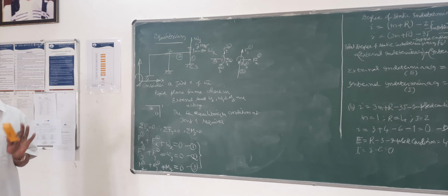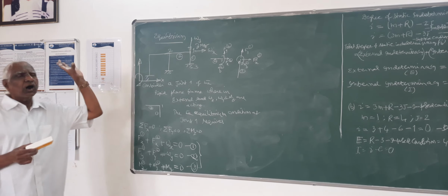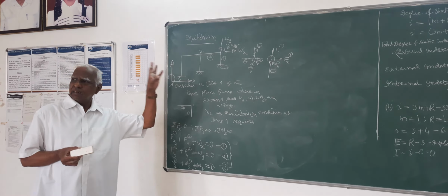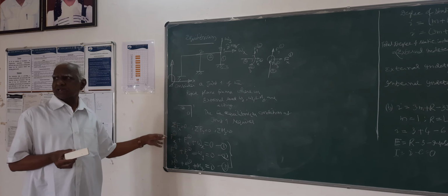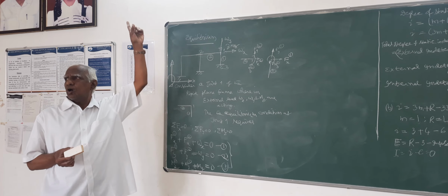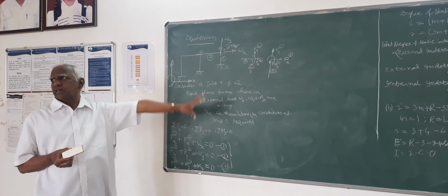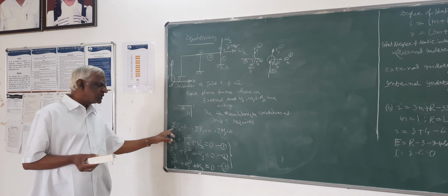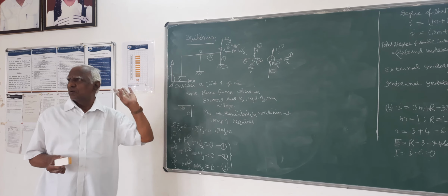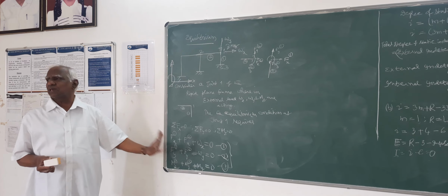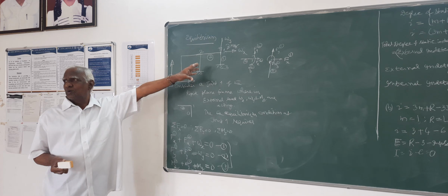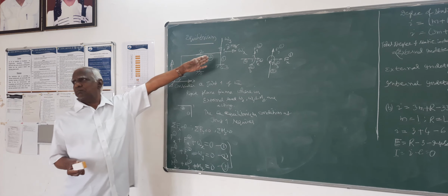This is what I defined as equilibrium conditions, applied at each joint of the structure. The equilibrium condition requires that the algebraic sum of all internal member forces meeting at the joint, along with the external loading, should keep the joint in equilibrium. That is, sigma Fx, sigma Fy, sigma Mz should be 0 at the joint 1. So this is the equation. This is exactly what I meant. This I have explained with respect to a general rigid plane frame joint.